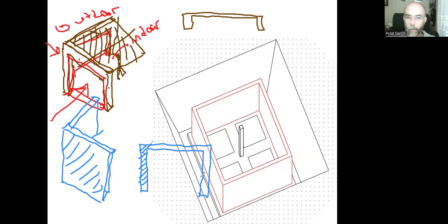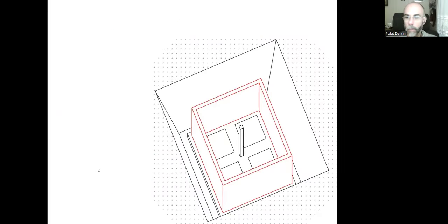So that's it. The loads of the floor will be directly transferred through these shear walls. There's no need for us to apply the loads to the beams and the beams will transfer them to the columns anymore because it's just one single surface. That's how we can create the basement floor.